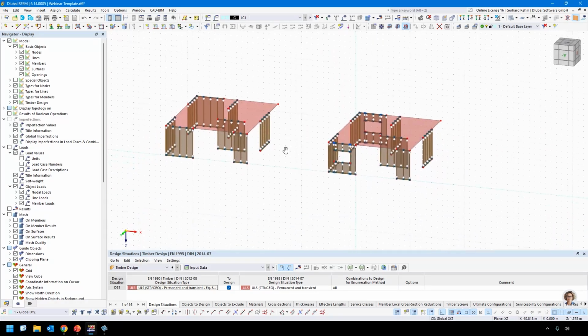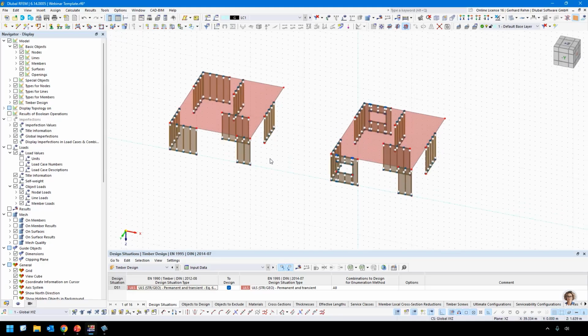So what do we expect now? We have two walls with openings. That means these walls are weaker. The ratio of this wall, I checked it in the PowerPoint on my second monitor, was about 70%, so there is still capacity left for this wall to take these forces.